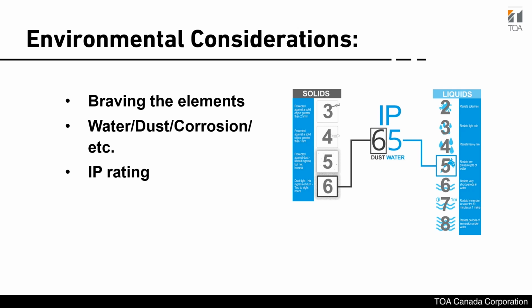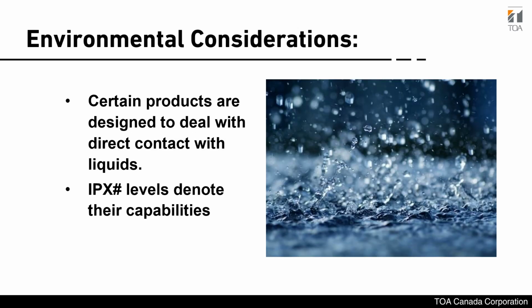Some systems face direct contact with water, requiring extra protection. Our outdoor speakers are designed to handle this, with ratings like IPX2, splash resistant, or IPX5, jet resistant like from a hose. Many of our water protection models include WP in their names, a common feature in TOA products.